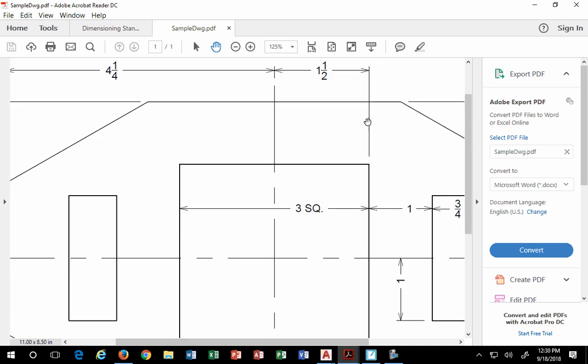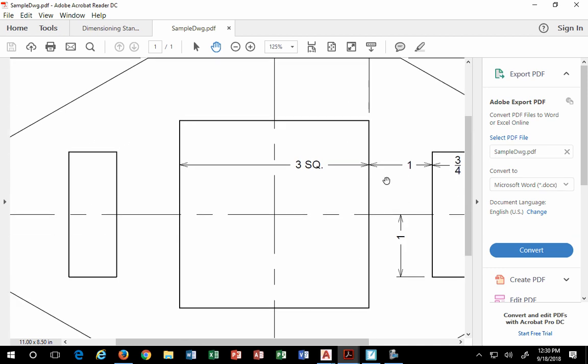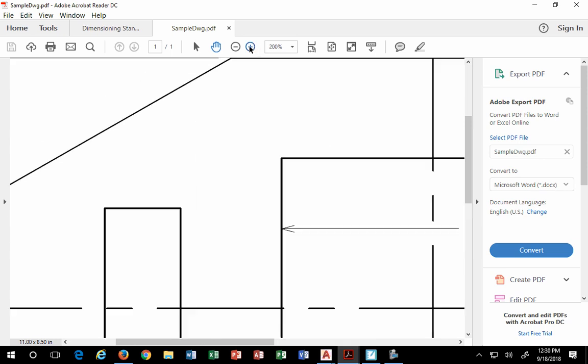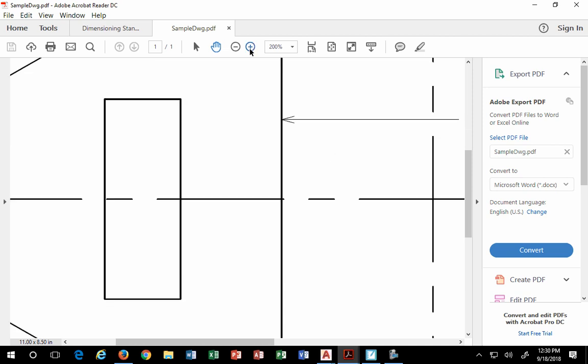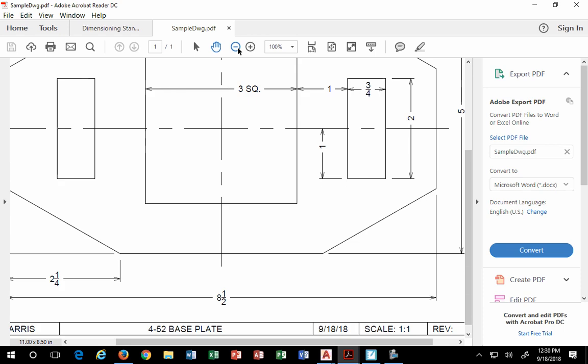And there you do see it, right here especially. Let me zoom in. There, you see it. See that distinct difference? That's what you want. Which means maybe 0.3 millimeters thick isn't thick enough. Maybe I want to make it 0.6. Got it? I leave that up to you. But you want to see that variance in the difference of the dimension from the object. Your object line needs to essentially pop.